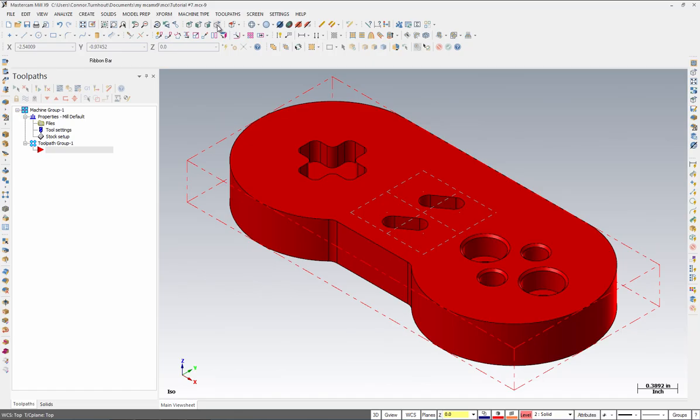Microlifts further refine the dynamic milling motion and avoid excessive heat buildup. The custom feeds and speeds optimize and generate safe tool motion. Dynamic mill machines pockets, material that other toolpaths left behind, and standing bosses or cores. The toolpath depends on the machining strategy that you choose in the chain options. The outside chain contains the toolpath. All inside chains are considered islands.